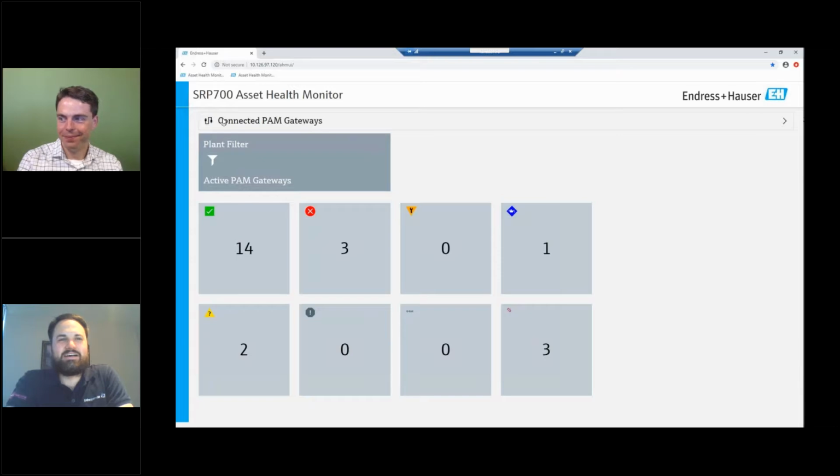Excellent. John Paul asks, in terms of security, can the access be password protected? So there are several ways to limit access. First of all, you can lock down FieldCare so that you need a password to log in to access device configuration. The second thing is there are technologies available to restrict the access to that web page, if you would like to do that.